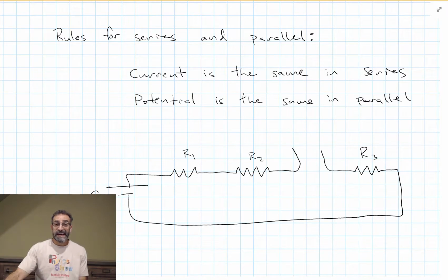That means I have to disconnect some of the wires from my circuit. Remember, when I hooked up my voltmeter, I could just reach in and clip the voltmeter on to resistor R2 in parallel to it. That was easy. But now, to measure current, I need it in series with R2. So I have to disconnect the wire that comes out of R2 and goes into R3 and hook it up through the ammeter like this.